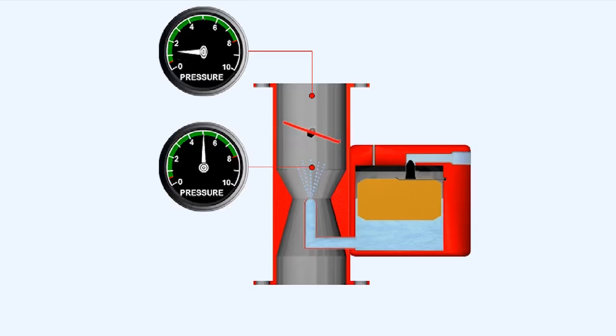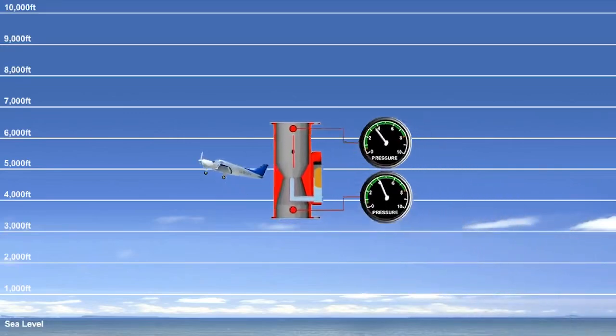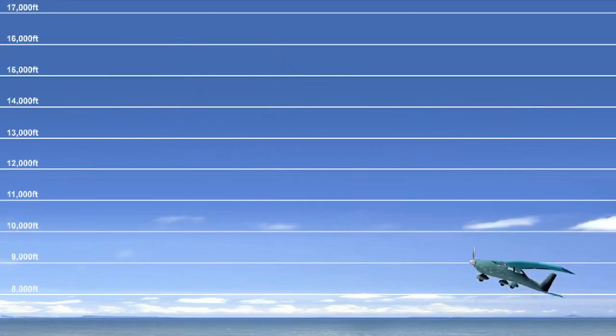The pressure within the induction manifold of a normally aspirated engine at full throttle is slightly less than atmospheric pressure. This is because of intake duct losses and the pressure loss which even an open throttle valve generates. We've already seen that the manifold pressure decreases with any increase in altitude. Engine power output of a normally aspirated engine, therefore, decreases with altitude.